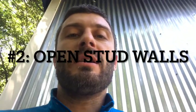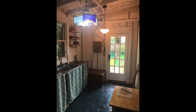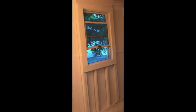The second advantage of external insulation is that this allows you to have the stud bays of the house open on the inside. So normally if you were insulating a house internally, you would put insulation between the stud bays. But if all your insulation is on the outside of the house, that gives you the option of not having to insulate your stud bays. And thus you can actually leave those stud bays open and create more space for the house and turn it into a design feature of the house that your stud bays are open, and you can actually paint your stud bays and make that the actual walling of the house.